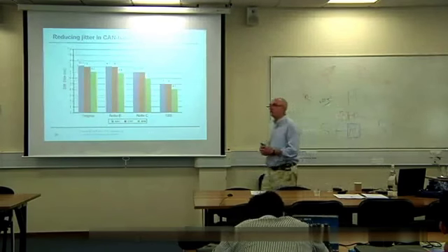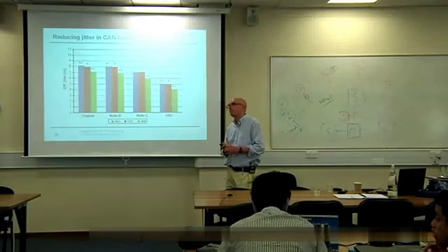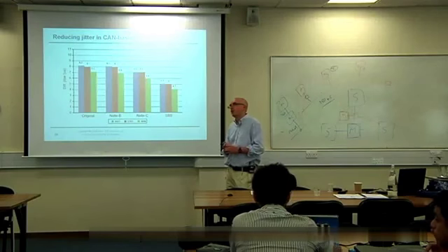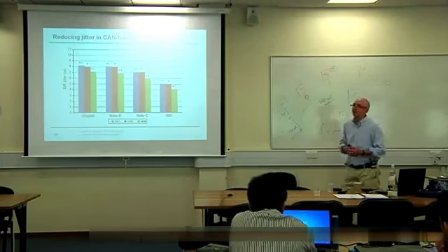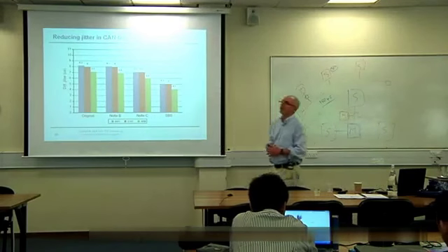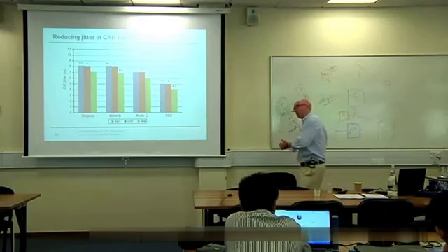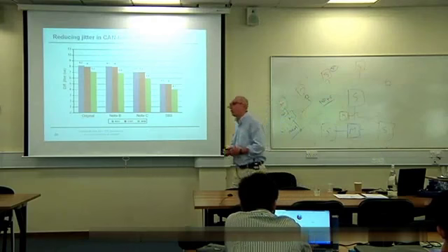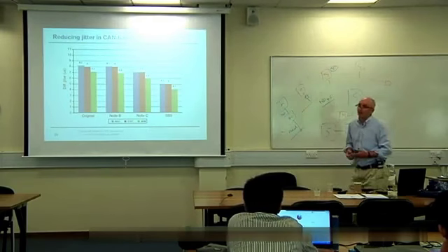Isn't CAN supposed to be deterministic? Well, what's sent on the bus depends on the message you put in. Yes. So it's deterministic in that it's a well-defined protocol, but the level of bit stuffing for a particular message that's sent at an instant of time will depend on the message contents.